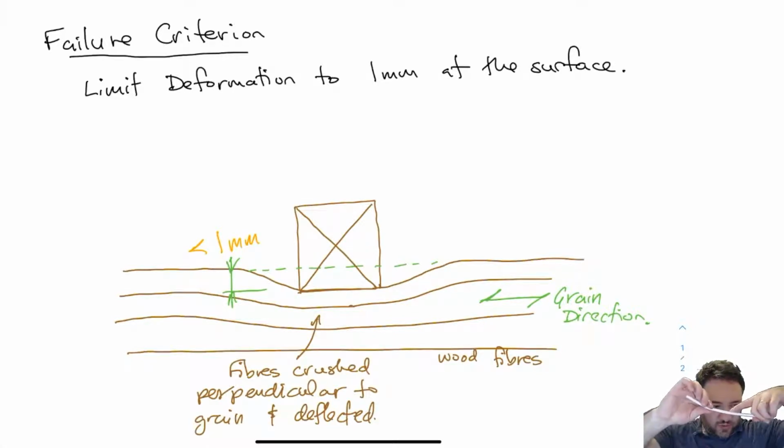But also when we're pushing down, there is a deflection happening as well, right? So the fiber at the ends is held up, and then in the middle, it gets deflected downward. And this provides some interesting local effects as well that we're going to account for in our equations, the fact that these fibers get deflected downwards.